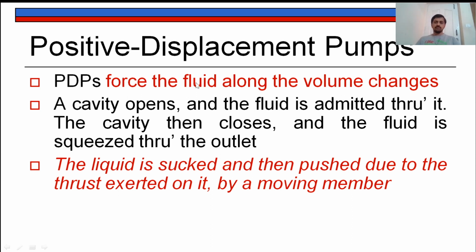So positive displacement pumps, or PDPs, force the fluid along the volume changes. A certain quantity of fluid will be trapped as a pocket of fluid and will be displaced. A cavity opens and the fluid is admitted through it. We will see in detail the working of the positive displacement pumps, such as reciprocating, gear, vane, or lobe pumps in the coming sessions. At that time it will be more clear to you.